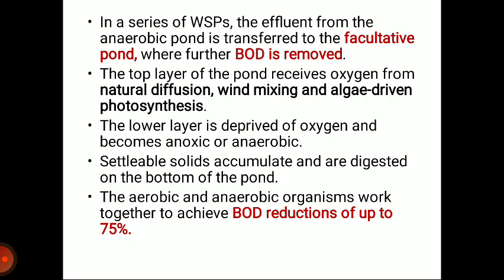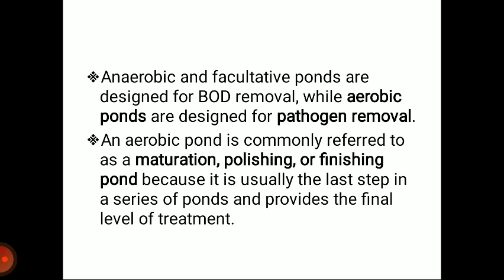The lower layer is deprived of oxygen and becomes anoxic or anaerobic. Settleable solids accumulate and are digested on the bottom of the pond. The aerobic and anaerobic organisms work together to achieve BOD reductions of up to 75%.